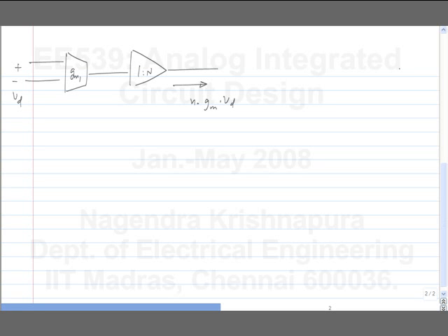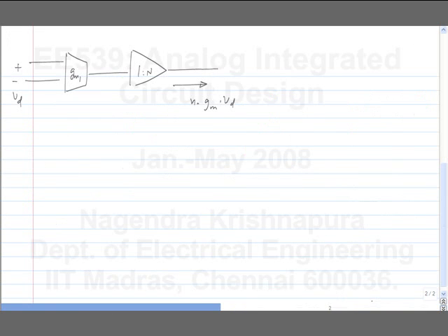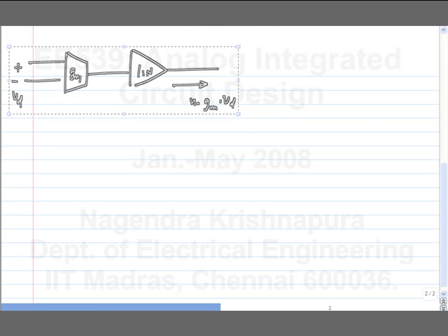Anything else? The bottom line is you are driving the CGS of those transistors, whereas in the other case CGS doesn't appear in the picture. And you have the extra pole. So the first topology where you fold it at the source tends to be better than mirroring the current. Anything else?